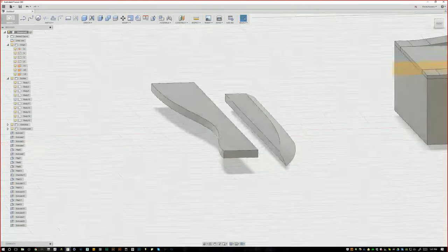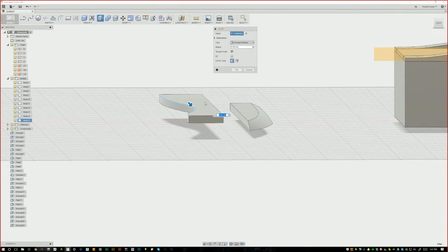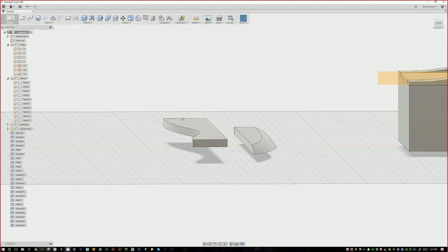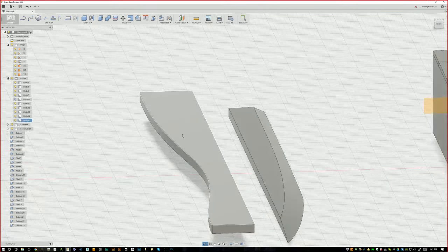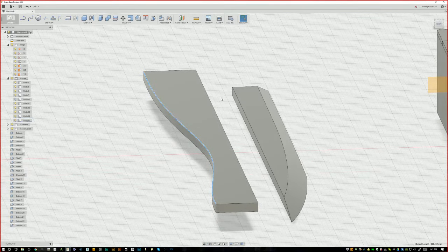Yep. So try this out. Go back into fillet for me. And a really cool shortcut, you hit the S key on your keyboard. It brings up a little shortcut bar. S key? Yep. Model toolbox? Do I need to go to fillet first? You could just type in fillet and it'll pop up. Type FILL in the model toolbox and it'll filter out.